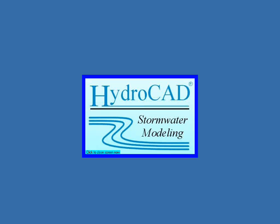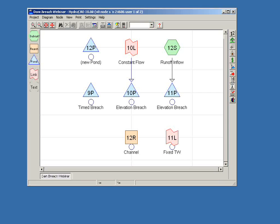Let's look next at a model in HydroCAD, which I already have set up with a couple of dam breach outlets. This will just save us a little bit of time in going through these. We have several different scenarios here. The first of these is a timed breach, so it is simply breaching at a specified time. We also have an example of an elevation breach, where we'll trigger when the pond reaches a certain elevation. And we have 2 variations of this. The first elevation breach is using a constant inflow. It makes it a little bit easier to visualize what's happening in the model. And then we'll look at an actual runoff hydrograph coming into the pond, where things get a little bit more interesting.